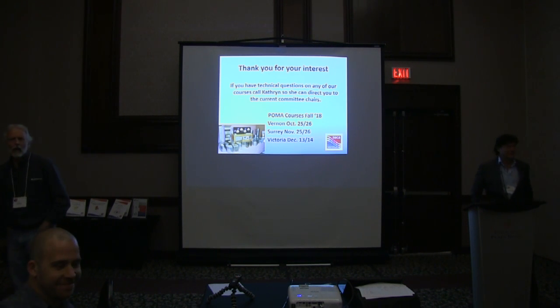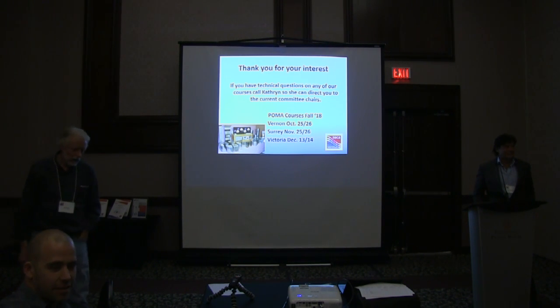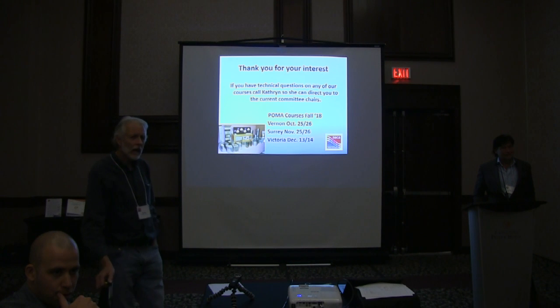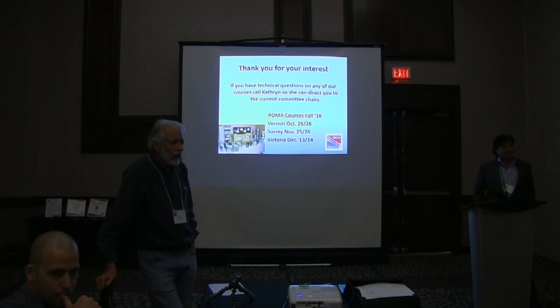The big deal is, I don't want to say ECMs are a myth. ECMs are fantastic motors for running at lower loads for long periods, for electrical cost. Commercial costs are a little different from homes. If you run a large motor down on low speed, you can run it on 40 watts. A PSC motor doesn't do that. A PSC motor runs at half watts, so that's the operating cost of the motor.